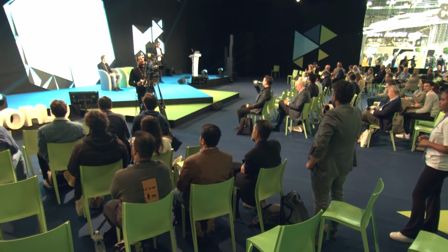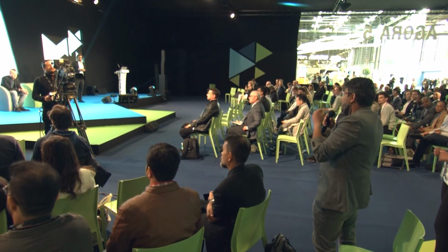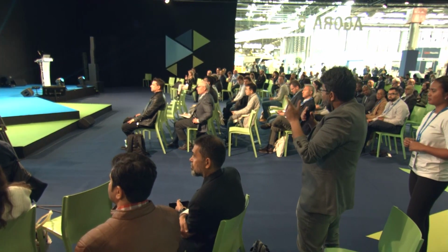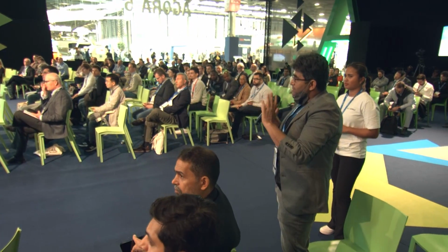Okay. The last question, just a curiosity, not a very technical question. About processing: carbon nanotubes, because of their morphology, like a fiber-like material, sometimes improve the viscosity of the material. Do you have some experience with this, how you handle this problem? Absolutely right. Any additive which has an extremely high aspect ratio, that means an extremely high length to diameter ratio, will give some viscosity enhancement.